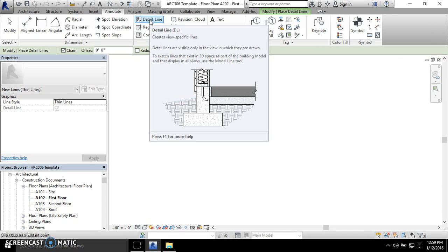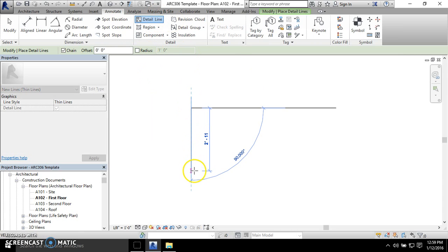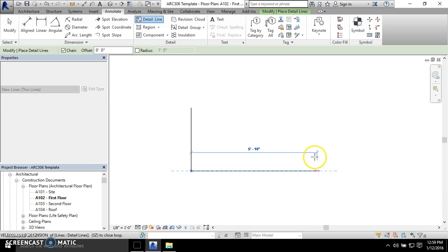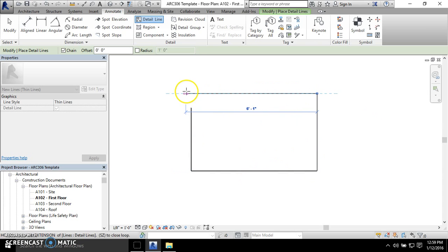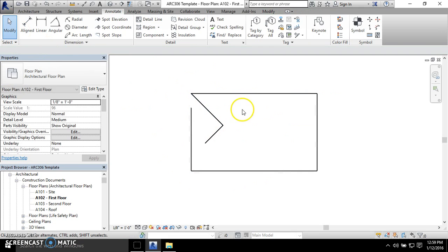So what you do is you take a section that you cut, and then you use this sort of stuff to actually detail and add hatch patterns, as you can see in the picture that I'm hovering over right here. But the detail line, if you wanted to quickly lay out or sketch a plan or something like that, you can use detail line work to do that and sketch anything out.